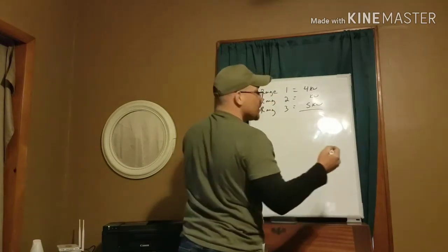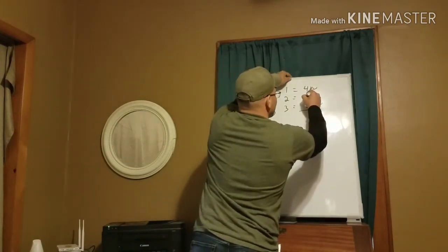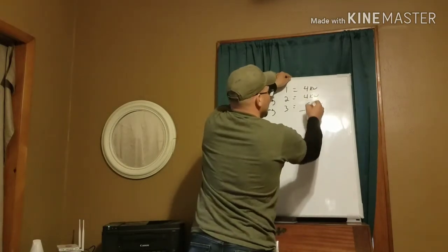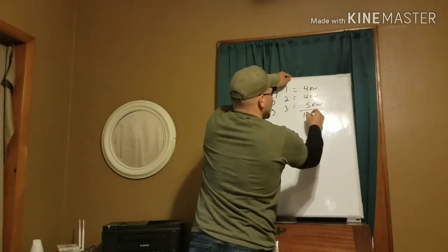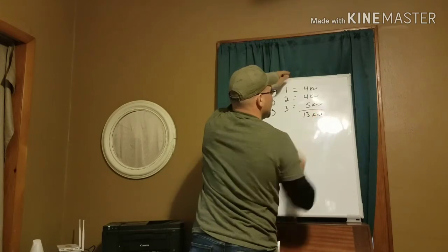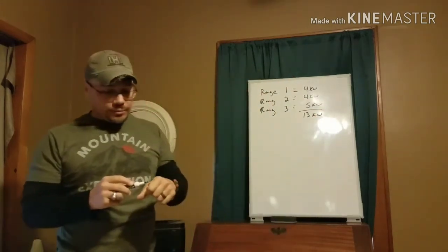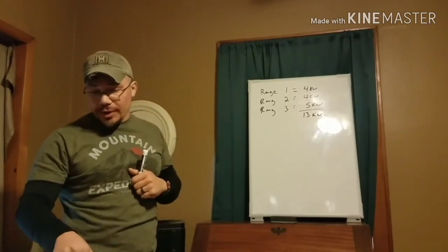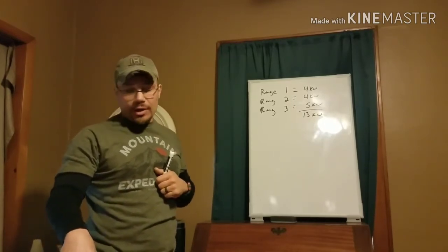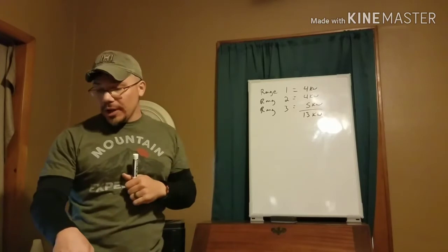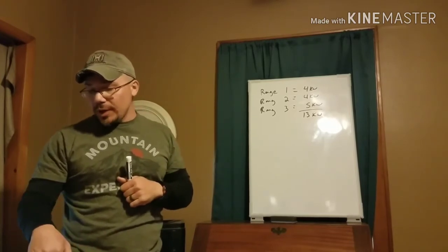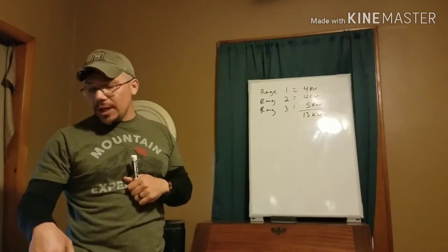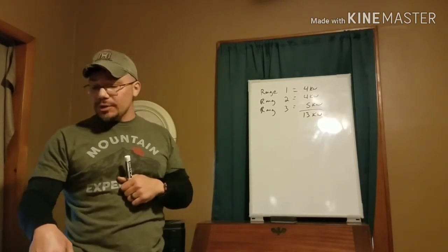So let me make it easy on myself. We're going to change that one to 4, and we're going to go 13 kilowatt, right? And so we go down to the 3 range for the number of appliances. We follow that across, since they're over 3.5, over to column B, and it says our multiplier is 55%.